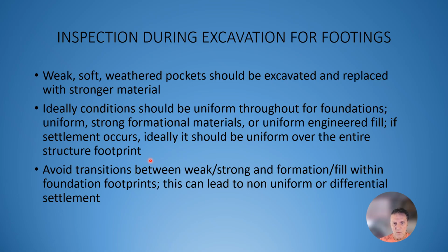And down here, avoid transitions between weak and strong, in formation and fill. In other words, let's say you are building on a hillside. So you have to cut the upper part and fill the lower part so that you get a flat pad. Now that may result in the back half of the lot or the pad being formational and the front half being compacted fill with somewhat different densities and properties.